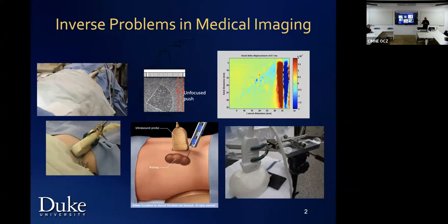You get a scattering from particles and fine structures of the tissue. You get the scatter field back, the intensity of that field, you plot it, and that's what you get. So bright images mean strong scatterers, dark means not so much scattering in a fluid medium, like the human body. That's an oversimplification of what ultrasound is, but it has most of the essence.